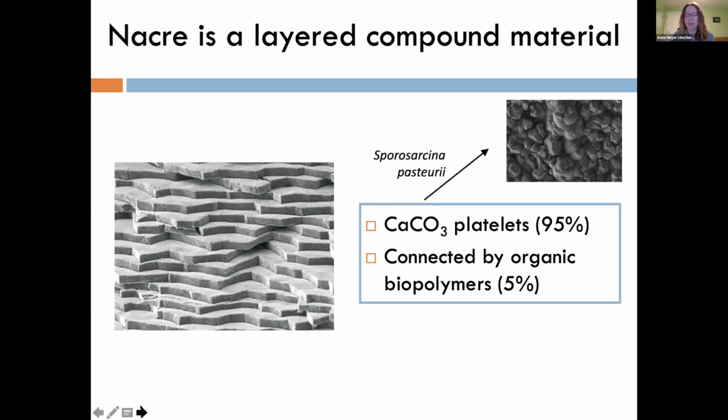So this is a picture of what happens when my student Dominic Schmieden took a culture of this bacteria, put a small glass platelet, like a microscope slide, in the bottom of it, added some urea and waited overnight until the reaction went to completion, and see what happens. We pull out the piece of glass and look at just the top view under a microscope. You see it's got this beautiful layer of calcium carbonate, of cement, covering the whole material. So this is how we can make cement with bacteria, really easy, just overnight on the benchtop.